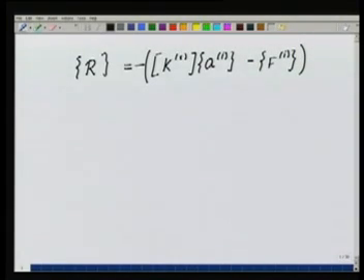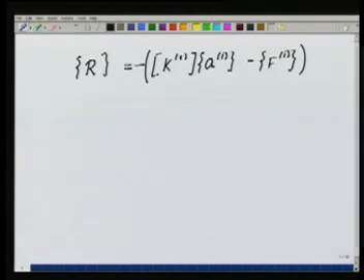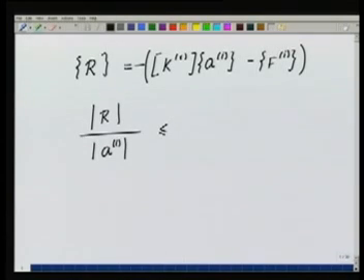So here, by putting the computed solution at the end of the step back in the calculation of the stiffness matrix, and taking the action of it on the computed displacement vector minus F, this is what we will call our residual, to be used in the computation of the error. And we had said that if the length of the residual vector divided by the length of the solution vector is less than or equal to some tolerance, then I stop.